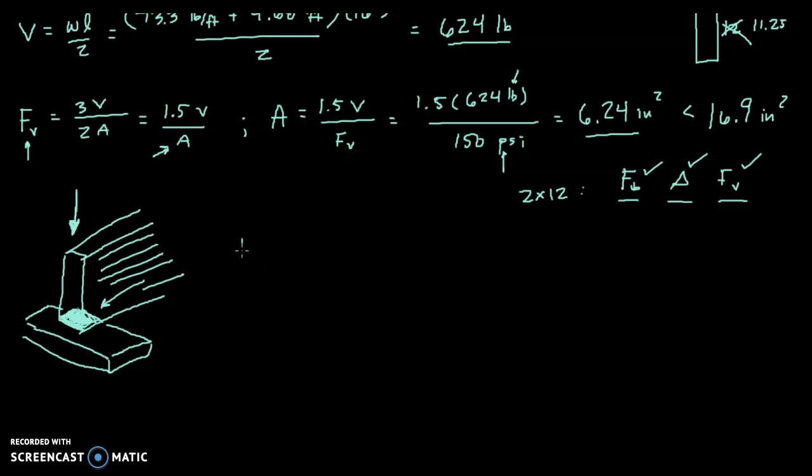So we have hem fir, that's the species of wood we're using in this example. And if we look up in Appendix F, it has properties of different wood species. Something we didn't write down earlier but perhaps should have was the F sub Cp. That is the allowable compressive stress perpendicular to the grain. And F sub Cp for hem fir is 400 psi. So that's not very large, but that's to be expected because wood generally is not very strong perpendicular to the